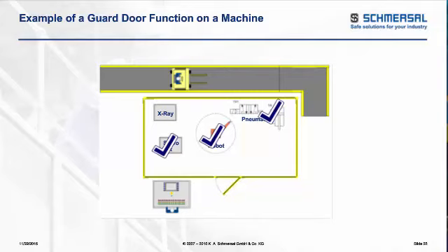We looked at dumping the air. We put a proper 3-2 safety dump valve on our main 80 PSI that came into the machine. We made sure the proper mufflers, the feedback circuits or switches or devices that are mounted to that safety valve are fed back into our circuit to ensure that the implementation is done properly per manufacturer's installation instructions.